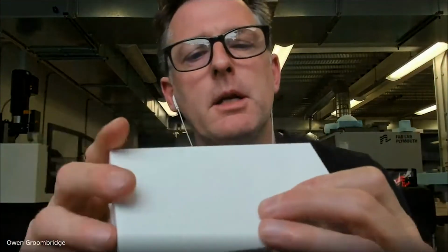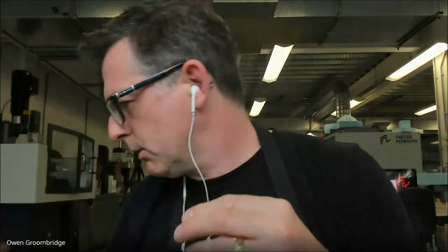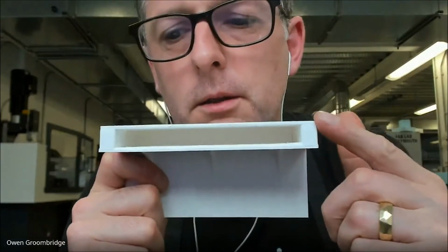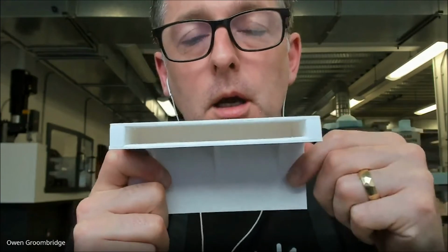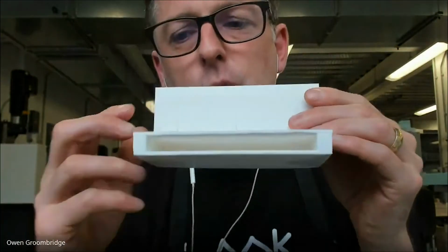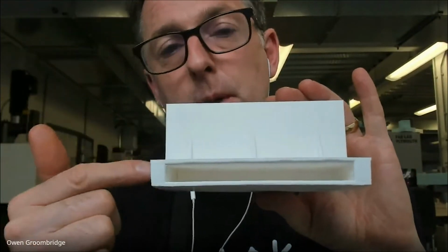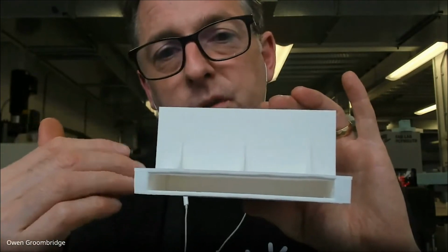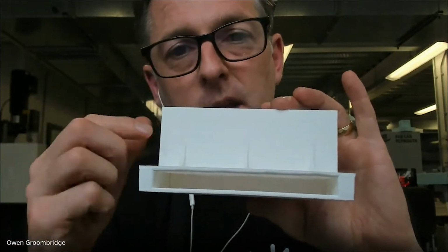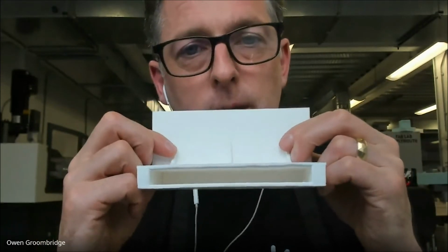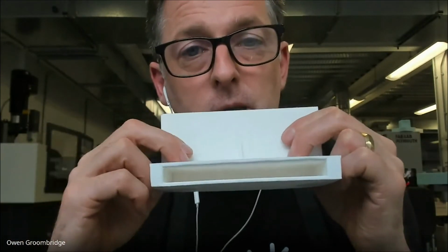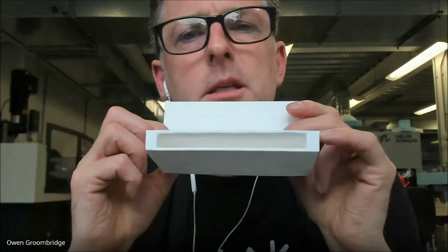Okay, great. The thing is, though, you might notice that this is a bad example. We find a good example. Oh, man. This is a good example. It's here. It's warped. It's warping. And what happens is that this was printed on a hot build plate, 60 degrees Celsius. And that heat remains, and as it gets printed, it also cools. So you get differentials in the heat, thermal differentials, and sometimes things lift, sometimes they just warp. It is a downside to this kind of printing.